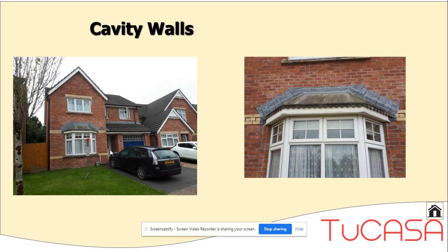We've been using cavity walls in cavity construction in our external walls since the 1920s and 1930s. How do you distinguish between cavity and solid by looking at the external wall? Well, have a look here at the arrangement of the bricks, and you'll just see the long face of each of the bricks on the face of the wall, which is an indication that you probably will have a cavity wall. We no longer commonly construct anyway in solid brickwork.